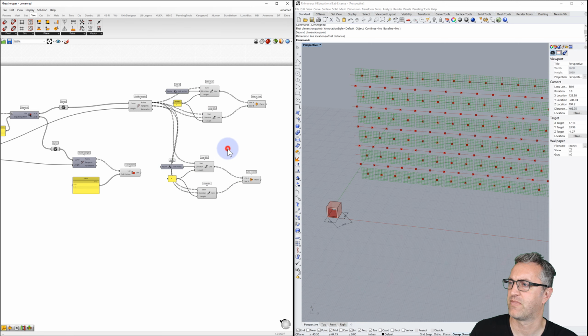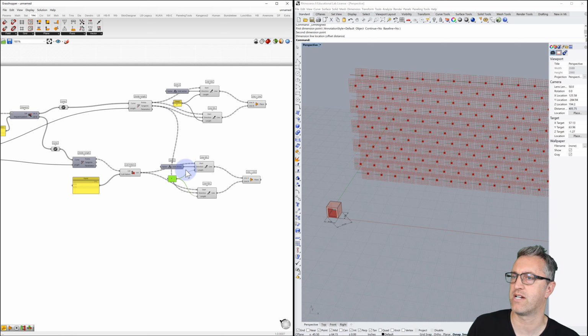We'll move it down, and we'll change a few of these things. So rather than using our points, we'll use this list as the start for each of those. The Z stays the same, and the 4 stays the same. We can tie back and use that 4 or not; it doesn't matter for what we're doing. The one thing that we have to change is the direction of our tangents related to our points, because right now it's pulling the tangents from above.